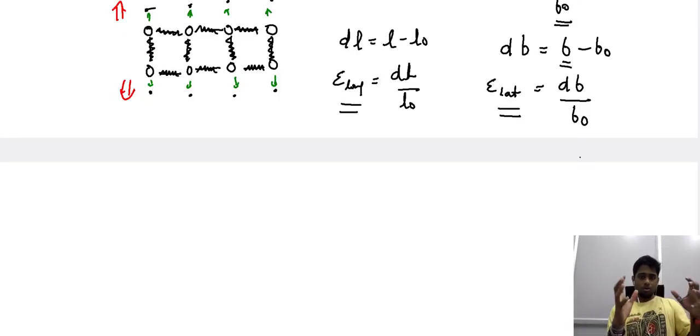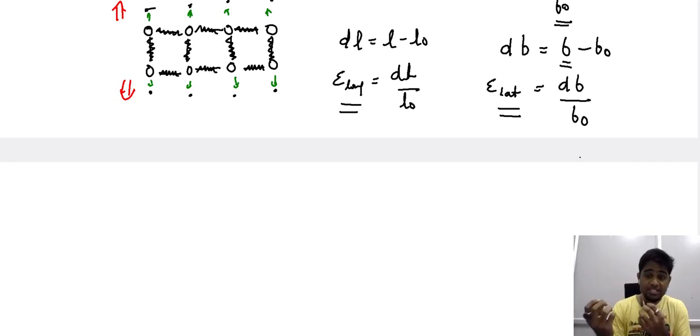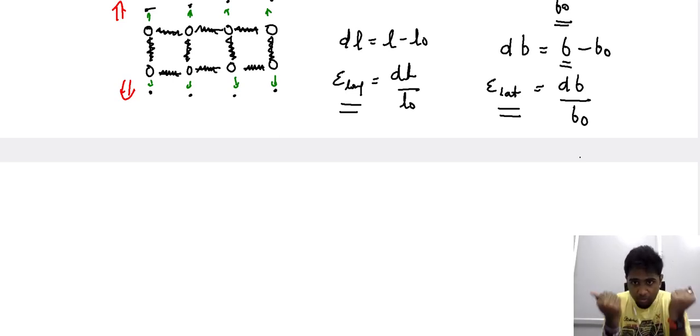Now we have extended our assumption, and we have an additional dimension to the strain that we observe, the response that we observe for uni-axial tensile loading. So far the uni-axial tensile loading has largely been confined to the change in the dimension along the longitudinal direction, and to that we have now introduced a parameter to describe the change in the dimension along the lateral direction. So we now have seen, for just one form of loading condition, there are two different strains that are possible.